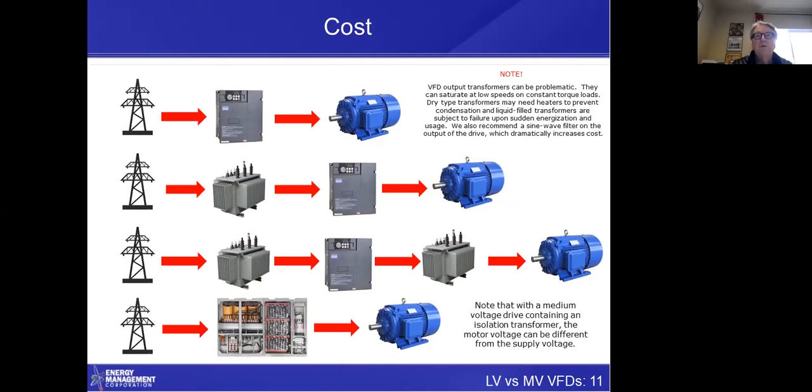So you're going to have to find a place to put it. Medium voltage drives can take power generally directly from the utility at 4160 volts, at 12470 volts. We'll use 12470 as an example because that's a pretty common utility distribution voltage. And if you do that, you really have to add the cost of that transformer, the pad, the mounting, the cabling, the relays, the protection, fuses, circuit breakers, and so on. You're going to have to add all that to the cost of your system.